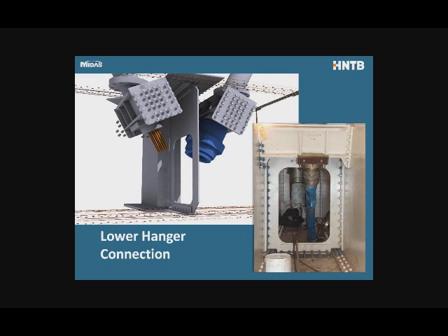Here's another view, a view of the bottom anchorage. This is also Blennerhassett. On the left, this is a rendering, because usually people get very nervous when you tell them you want to stress these large cables from inside a box. Blennerhassett was actually quite generous with 7 feet by 4 feet. We'll show you Lake Champlain in a moment here. So the left is a rendering where we tested out the equipment, and the right is with the strands installed.